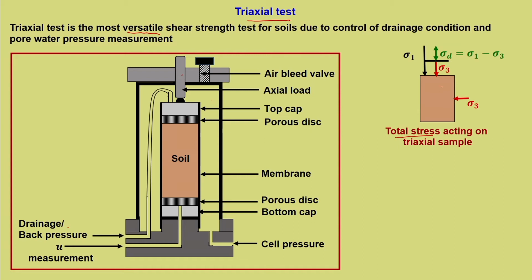Now, in triaxial testing, it is important to understand what causes failure. So, initially there was a confining stress sigma 3 all round. This stress will not partake in the process of failure, because this is an isotropic stress condition, the mean stress condition where all round stresses are equal. Now, this creates volume change, but not shear stress within the soil. This we have already discussed.